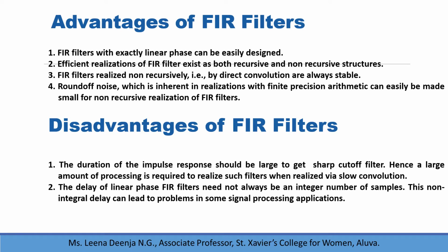Advantages of FIR filters. First advantage, FIR filters with exactly linear phase can be easily designed. Second, efficient realizations of FIR filters exist as both recursive and non-recursive structures. Recursive means a system whose output at any time depends on a number of past output values as well as present and past input values.